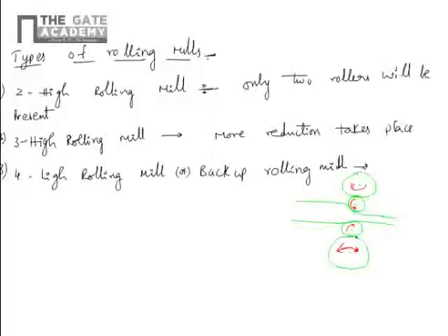This one's rotation is opposite. If it is rotating anti-clockwise, this one rotates clockwise. Sorry, yeah. Power is given to the smaller rollers, not the bigger rollers, because the shaft won't take it. To avoid shaft failure, we use this.